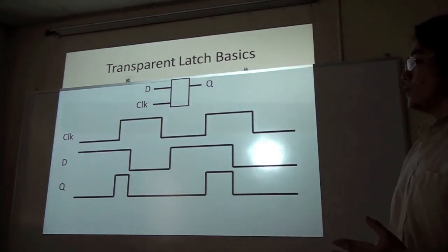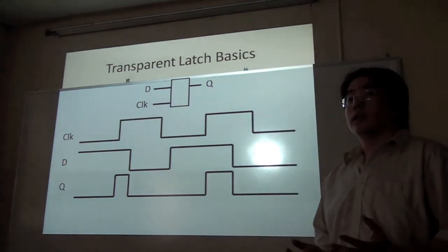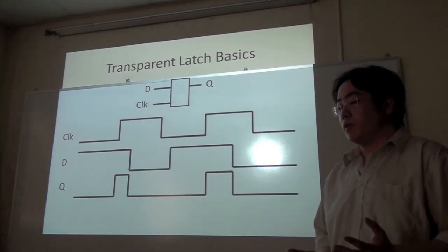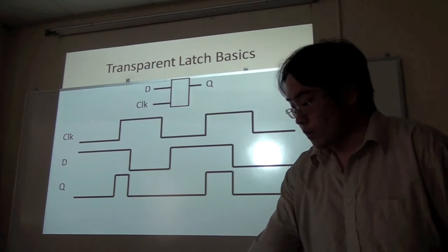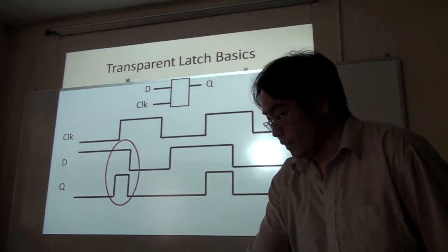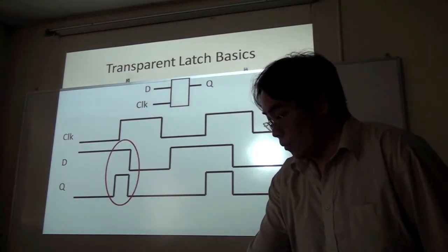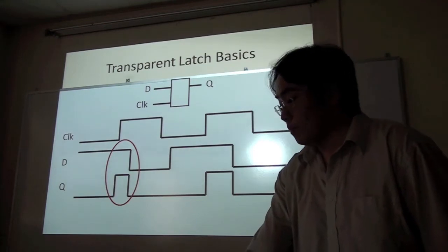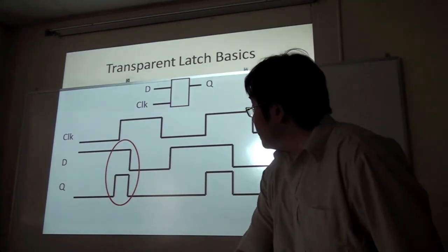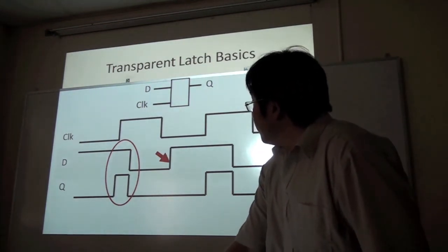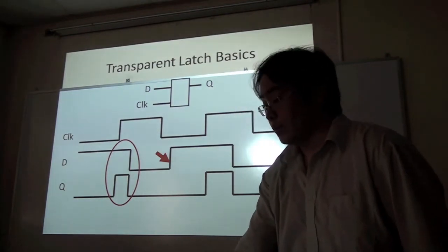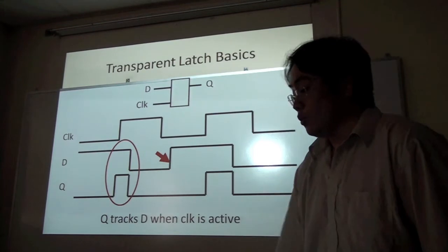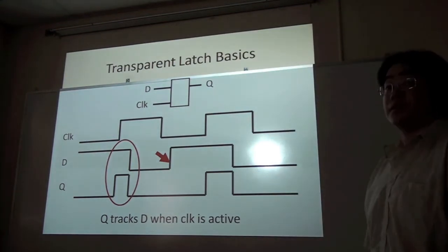Before I talk about how we use latches, I'll first give a brief overview of how a latch works. When the clock is active, Q essentially tracks D. And when the clock is not active, Q does not react when D changes. So essentially, Q tracks D when the clock is active.